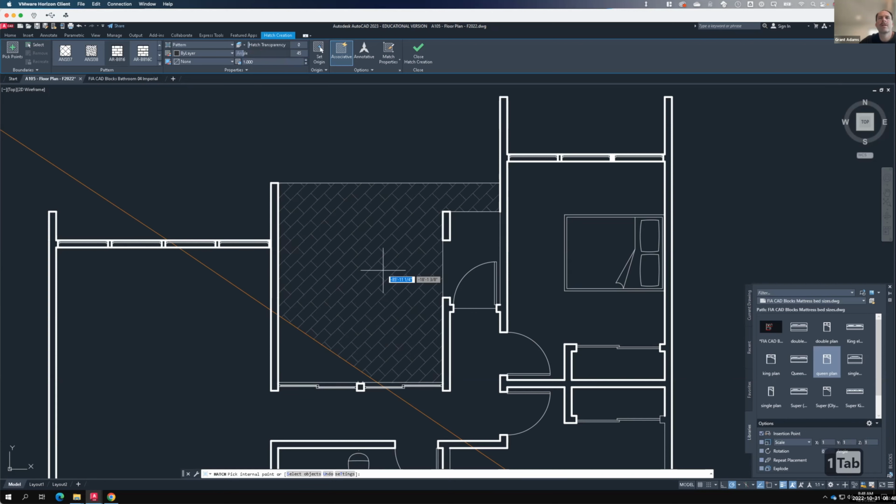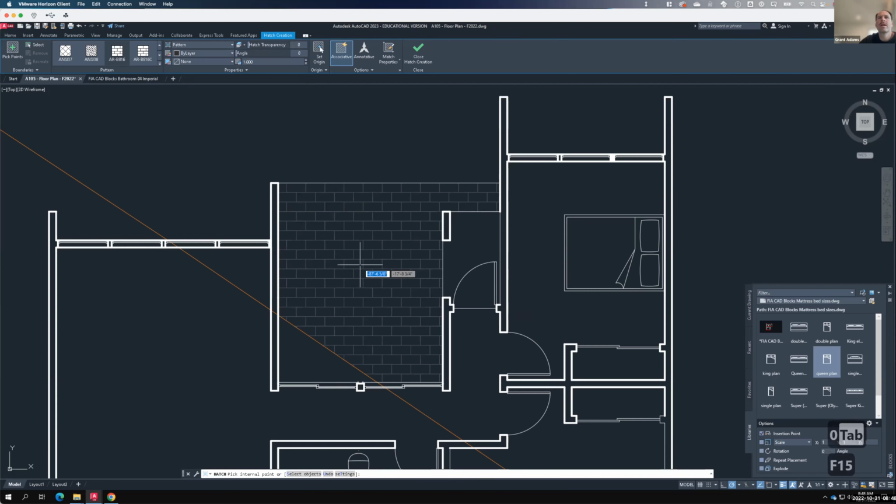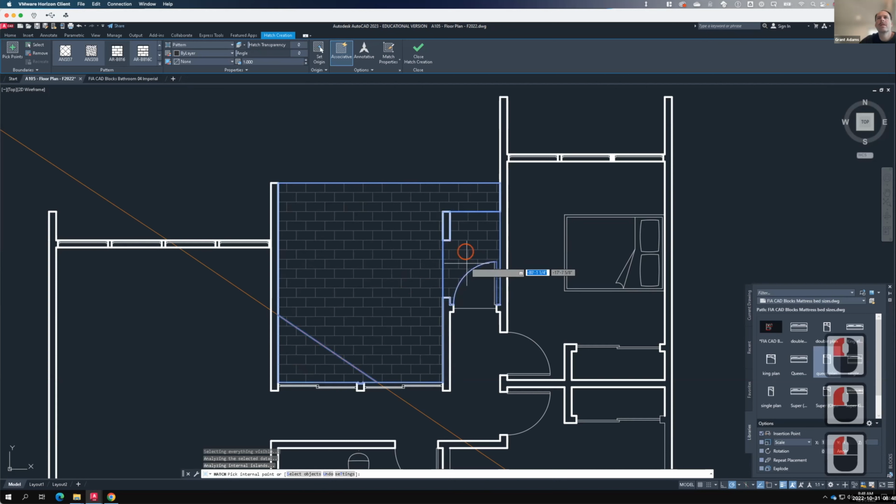There you go. That's not too bad. But again, it's at an angle. So let's switch it so that it's at 0. And then I could fill this patio as if it were little concrete tiles or pavers or something. And we can fill in those regions right like that. And then I can go ahead and hit enter to finish.